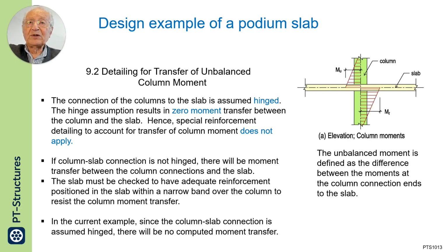I mean, the moment calculated for the slab includes, I want to repeat, the program you use. Even if you use hand calculation, the moment that you obtain at the face of the column in the slab already includes the unbalanced moment, and the reinforcement for which you design the slab already includes the reinforcement necessary for transfer of unbalanced moment.